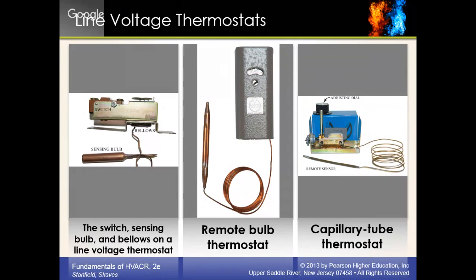Air conditioner. Remember that? Remember us reading about that? Where the air conditioner just has a dumb pressure switch on the condensing coils, that if the pressure gets too high, it's probably right in line with the condenser. So the power for the condenser is going to go through this pressure switch.